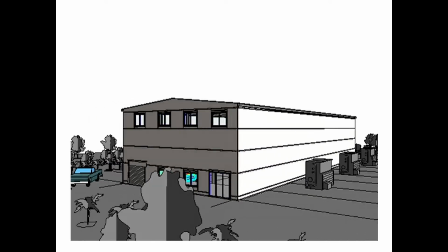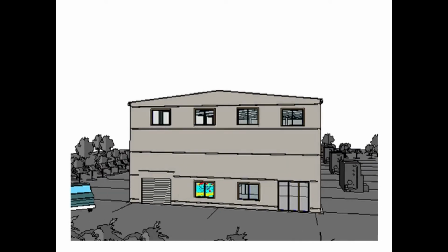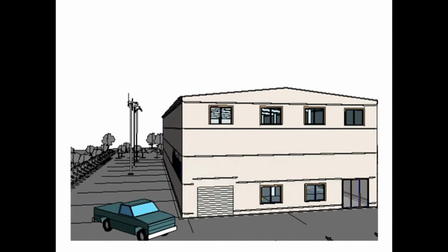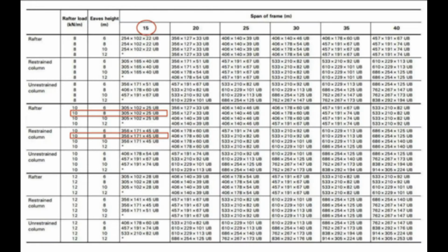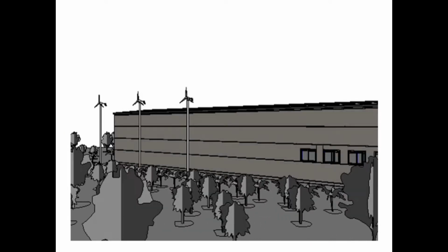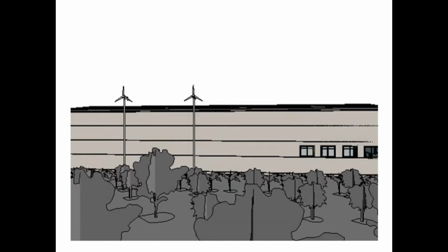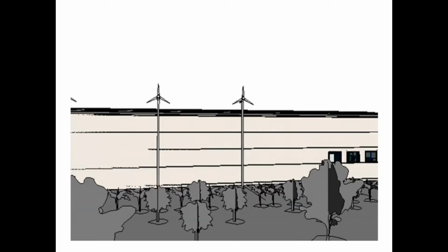Using the given BIM design brief, we can use our building parameters to allocate the correct size universal beams for both our columns and rafters as highlighted above. Additionally, Group 22 has been allocated Region B for wind loads. This gives the appropriate spacing for the purlins and girts.